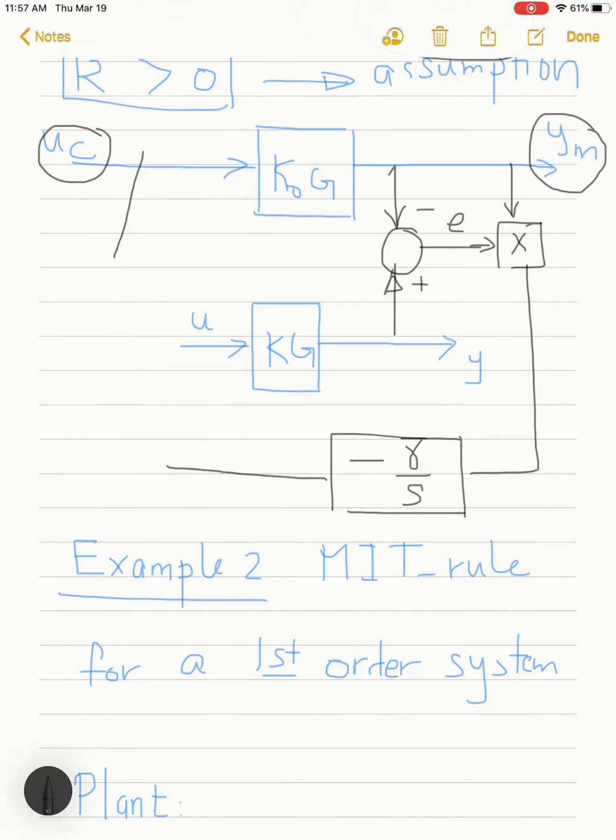And the result of that would be theta. So what I have here as an input is an expression for theta dot, or d theta by dt, and then the integration of that would give me theta, and this value of theta should be multiplied by the set point in order to produce the actual value of the control signal.